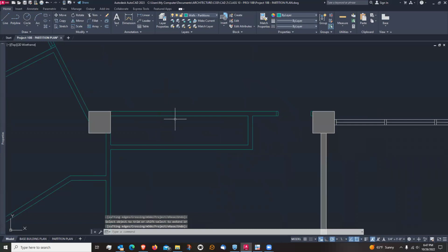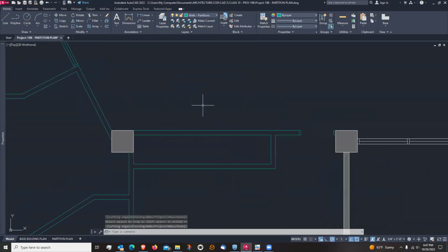Okay, so now we got 4 doors. Well, how big are the doors? Well, let's see. I just said that commonly doors are 3 feet. Sometimes for closets they're less, but let's see how big our closet is. So it's 12'7" wide. So if we have 4 3-foot doors, that gives us 12 feet, and that gives us 7 inches or 3.5 inches of jamb on either side. So let's just do that.